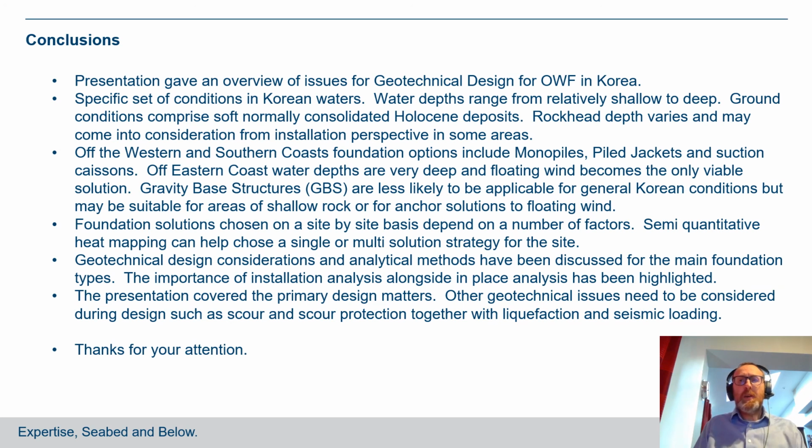The use of heat mapping as a semi-quantitative method for foundation selection for a particular site was discussed. And then we went on to the real meat of it and talked about different geotechnical design considerations and analytical techniques for different foundation types. We didn't really have a lot of time to touch on other geotechnical issues, but scour and seismic issues such as liquefaction and seismic loading also have to be considered.